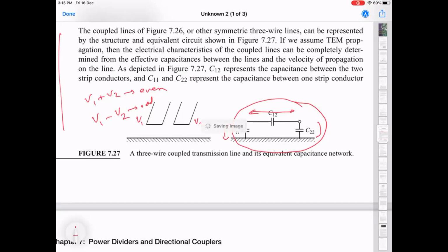Which was the circuit we analyzed using the even odd mode analysis? That was the, sorry, what was the first circuit we used? Oh, the Wilkinson divider, right? So there you saw this idea that if you excite the even mode, everything remains in the even mode. It will not transfer into the odd mode. In fact, that is the meaning of, when we call them normal modes, that they are non-interacting. So it allows you to calculate the properties of the things separately.